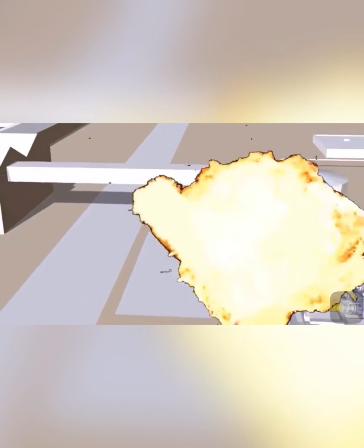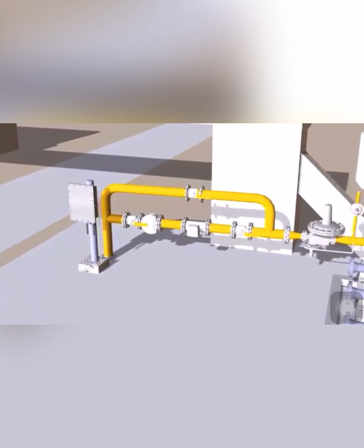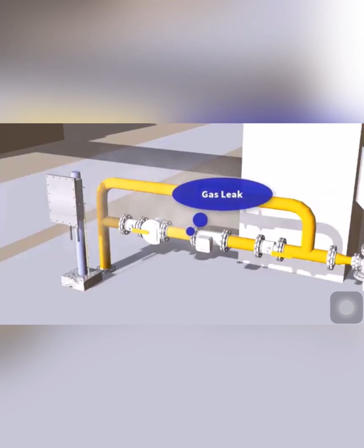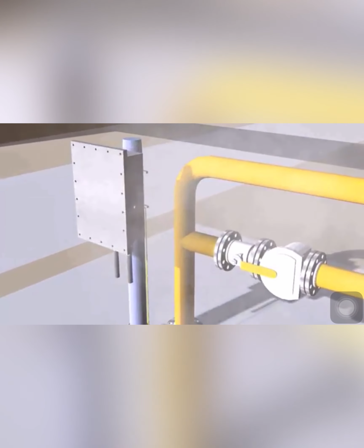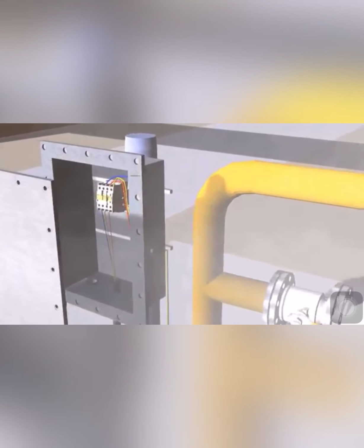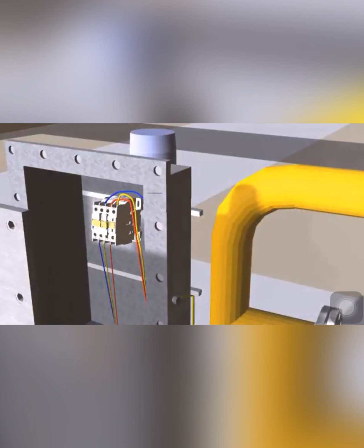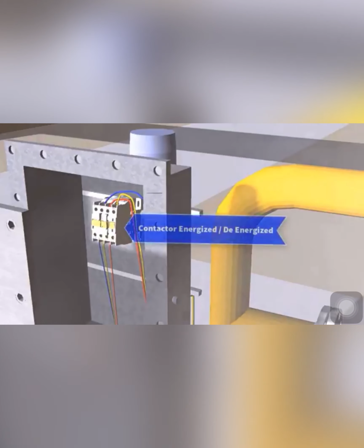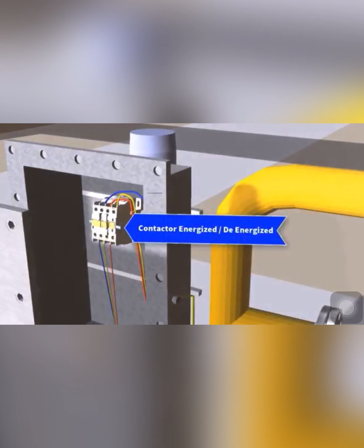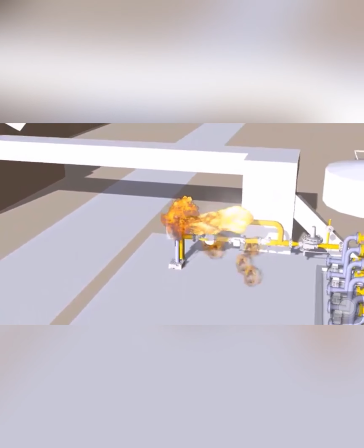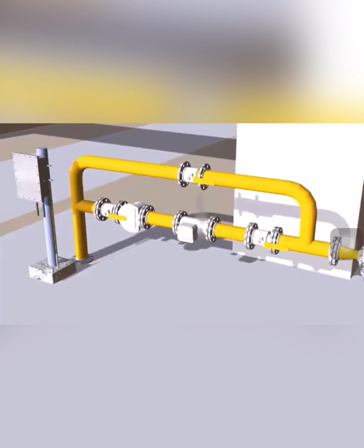The classification of potentially explosive area into zones, the frequency and the duration of the occurrence of a hazardous explosive atmosphere, and the local environmental conditions forms the basis for defining the level of protection for equipment. It is furthermore necessary to know the key explosion-related figures for the flammable materials, such as temperature classes, dust ignition temperature, explosion subgroup, and etc., as well as the local ambient conditions.